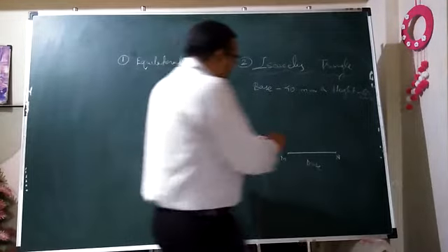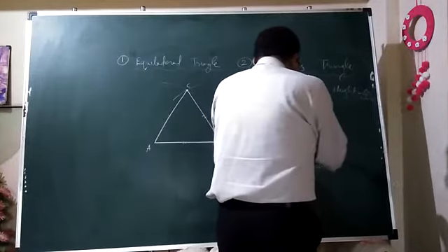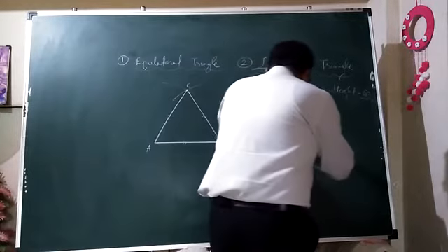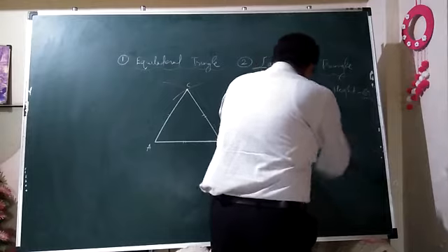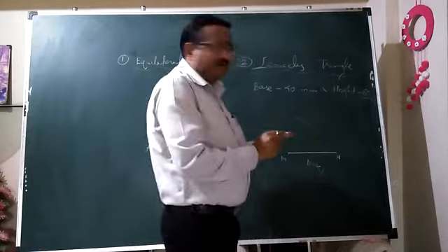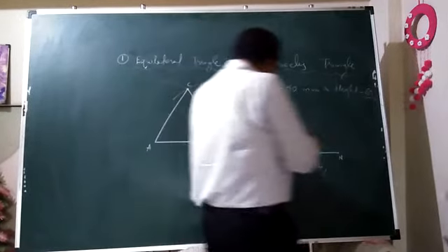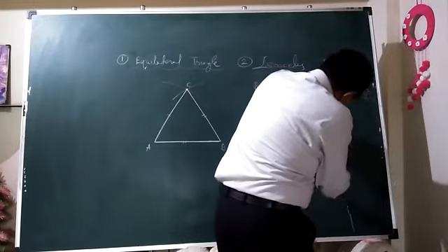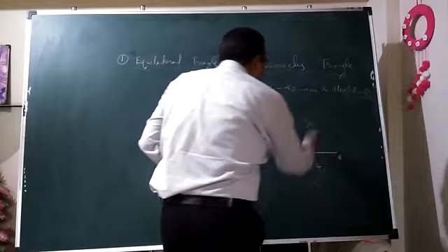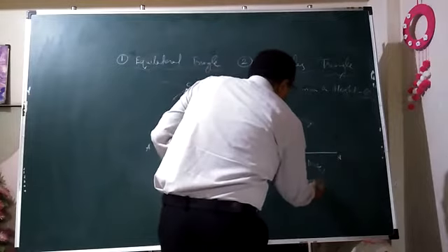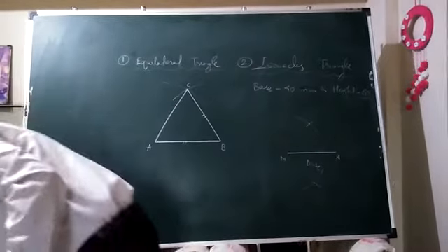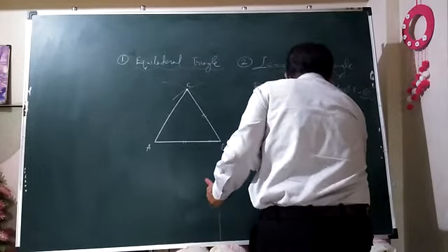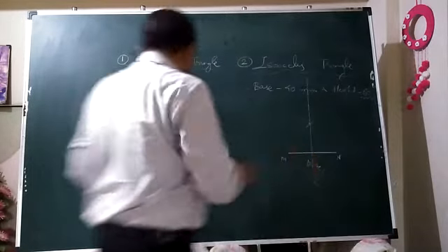We have learned that construction last time. So more than half of the distance in the compass you have to pick, and draw intersecting arcs above and below the line by interchanging the position of the needle. First from M, second from N. Get intersecting arcs, and in this way both the intersecting points we have got here, that you have to connect and extend it upward.